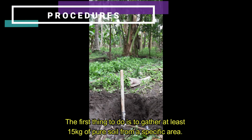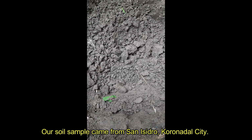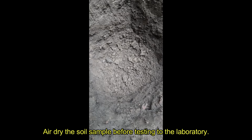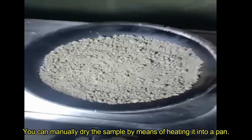So, the first thing to do is to gather at least 15 kilograms of pure soil from a specific area. Our soil sample came from San Isidro, Koronadal City. The soil sample must be at least 1 meter below the ground. Air dry the soil sample before testing it in the laboratory. You can manually dry the sample by heating it in a pan.